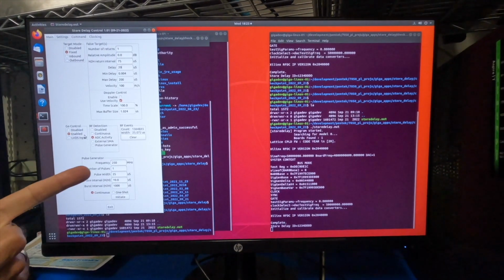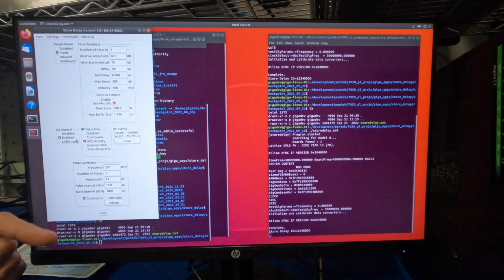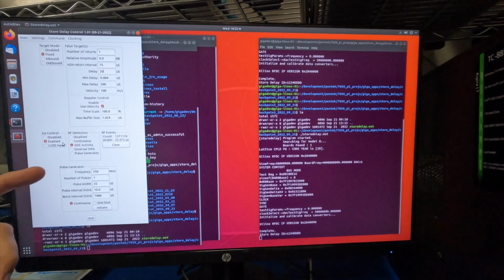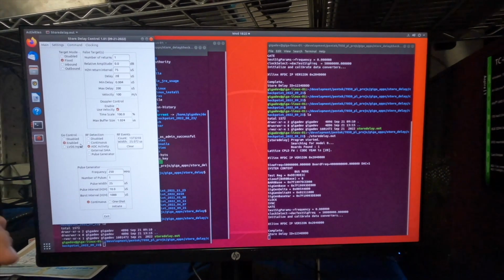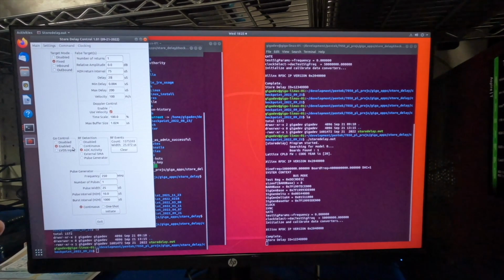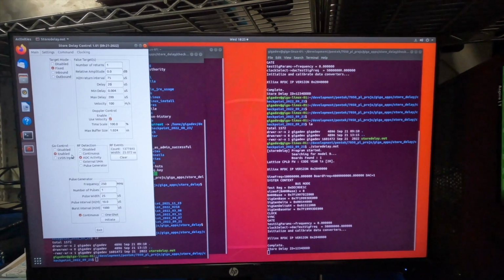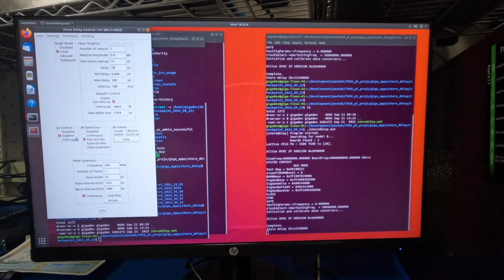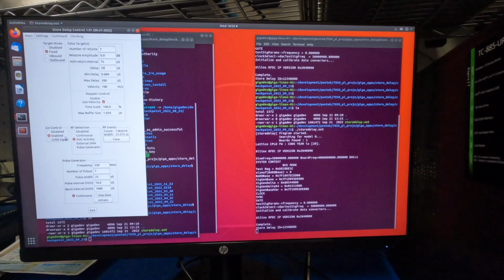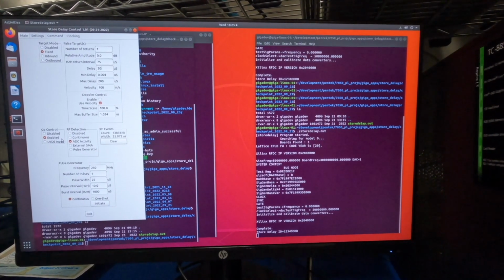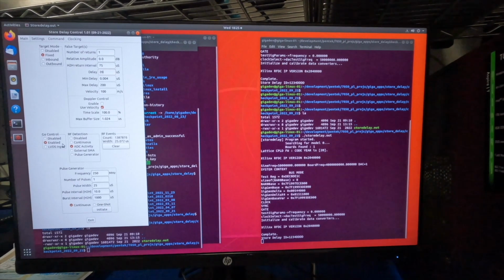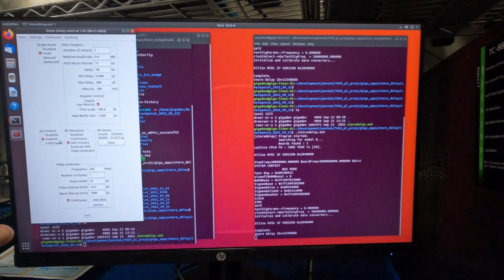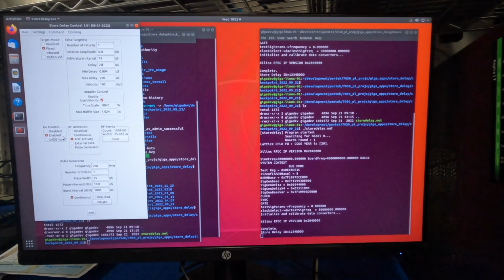So the signal we're going to be putting in for the DRFM jammer to capture is centered at 250 megahertz. We could run it at a much higher frequency, but to show it on the scope, it makes it easier to do. Right now we're only putting out one 25 microsecond pulse in a 1000 microsecond, or 1 millisecond, pulse repetition interval. And the interval for the dwell, if you will, is 1 millisecond, and we're just using that to show the update rate on some of the instrumentation. It could be a much more complicated waveform than that, but that's just for the demonstration today.